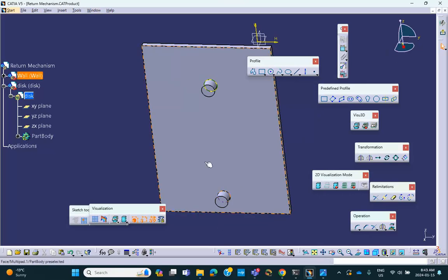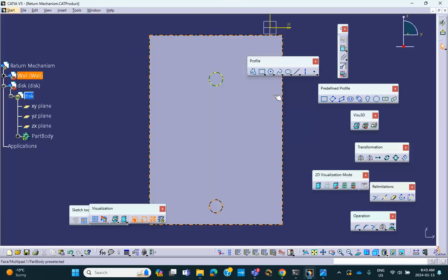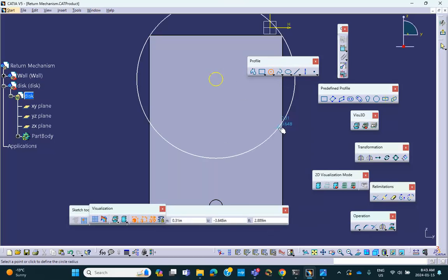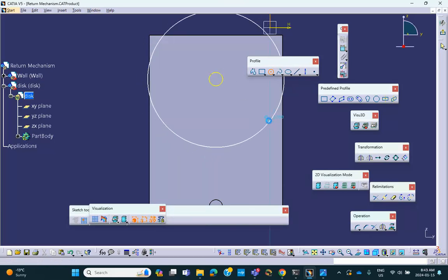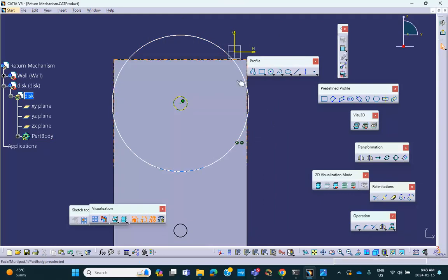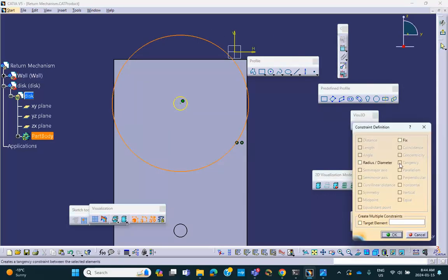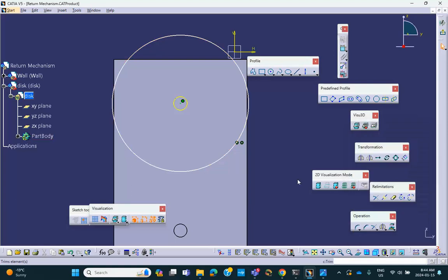And then add the other piece to it. So what do I mean by that? Normal view here. Draw another circle concentric with that. This is going to be the disk. Now, if I'm not sure that this is concentric with that, I can select them and make it concentric, but I can see that they are concentric, I think. So let me check that. You see that? It's already concentric. There's nothing to cancel out.